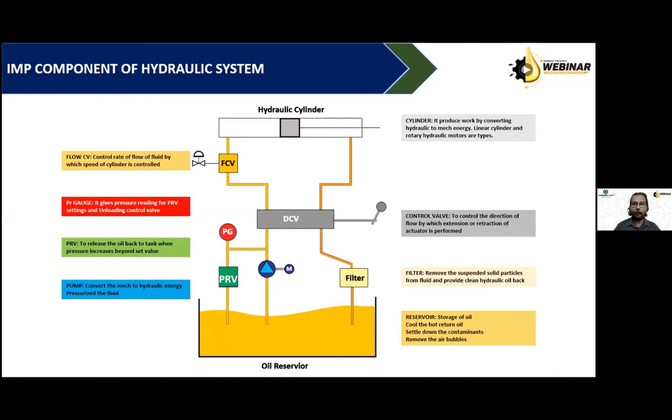Now oil enters into the cylinder arrangement where we have seals, and when the piston does to and fro motion, the contaminants stick on the cylinder surface, or cylinder liner, we call them normally. They cause small scratches on the liner or inner surface of the cylinder, as well as piston seals.